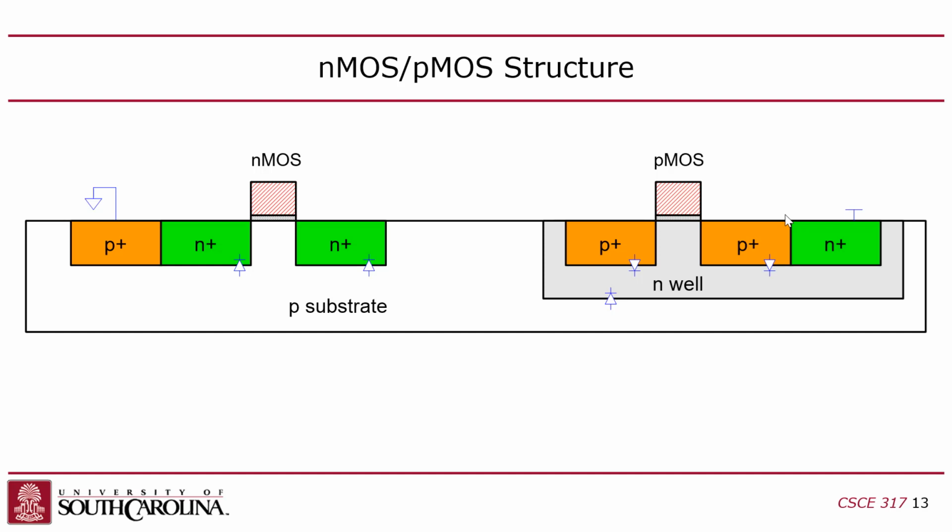And then I can make sure this substrate's grounded, right? Then, over here, when I have a well, the well is N. I put some N plus on there to make a nice little transition. And then I connect this N plus to my wire. Wire goes to VDD. So that'll let me take this N well and take it to VDD, right? Make sense?